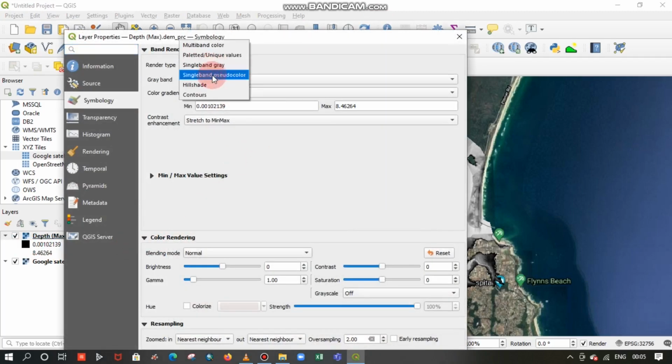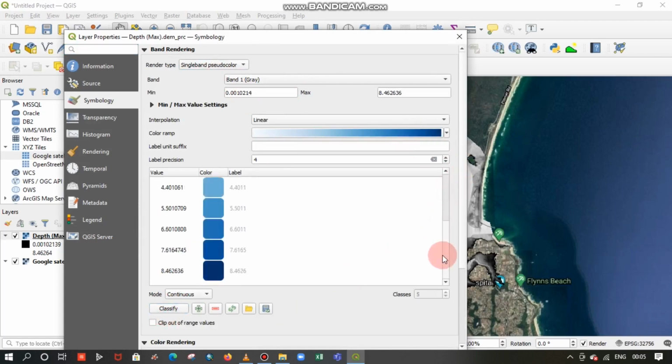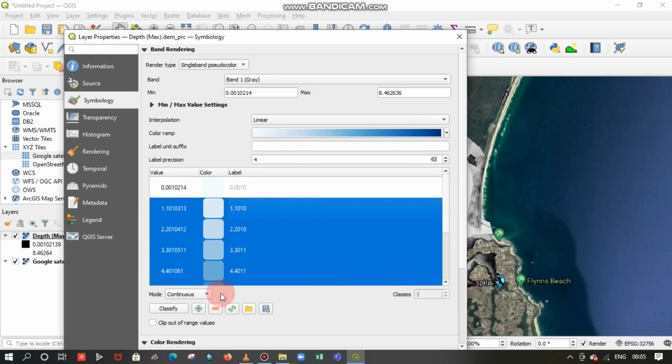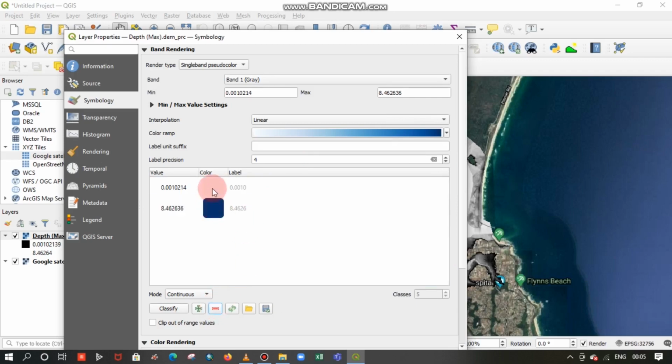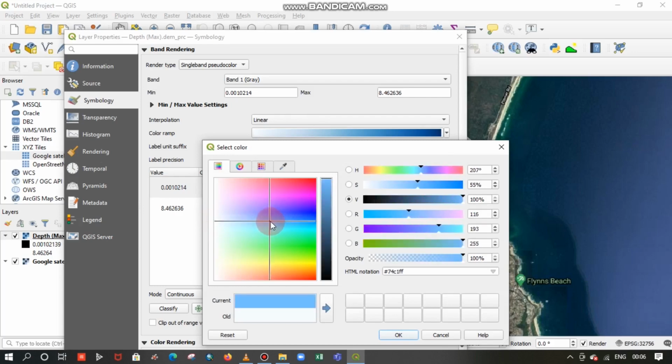Okay, so we can observe the flood inundation map. Here you can see it. So now move to its properties. In the properties, change to single band pseudocolor and classify the ranges. So I will keep two color components. So select the rest of the others and remove them. So you can see the color code has the two color component variation.